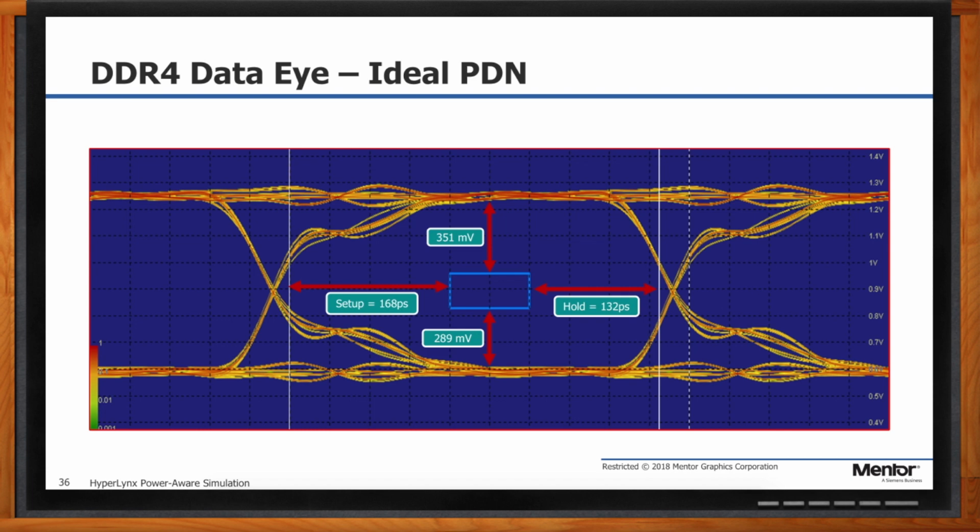So here's a baseline analysis, right? We run that wizard I talked about. We idealize the PDN, so we just make it ideal. It's typical standard analysis. And then we look at how much margin we have vertically and horizontally, how good are we? Then the next step is we'll take the PDN and model the real PDN.